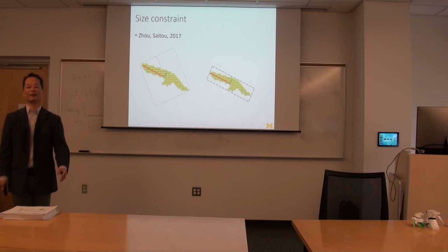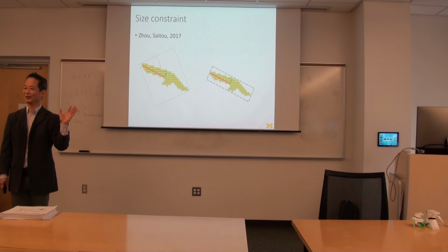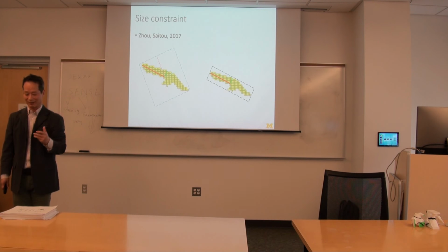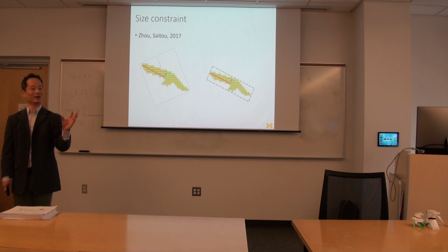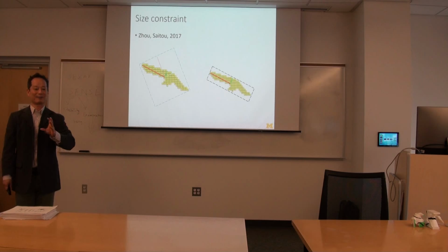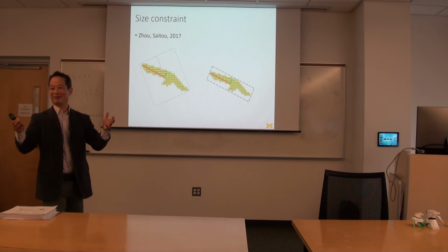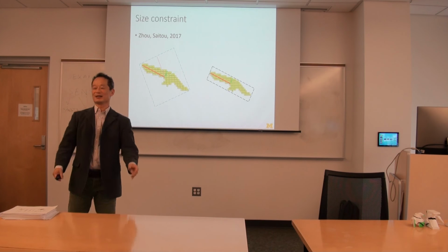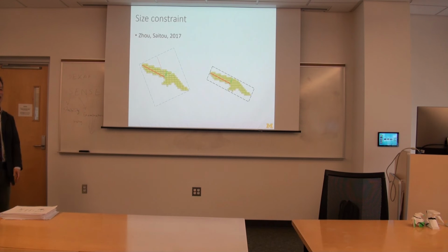So if you figure out only a handful of geometric properties to be constrained, they can be applicable to a wide range of manufacturing processes, with of course some tweaks, but the principle is astonishingly small. One of those is, of course, the size. Size matters. Typically you have a machine limitation, or maybe the cost of the machine is expensive if the parts are big. So being able to impose a size constraint is important for many classes of manufacturing processes.